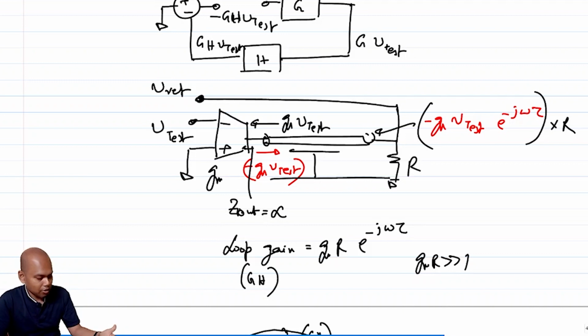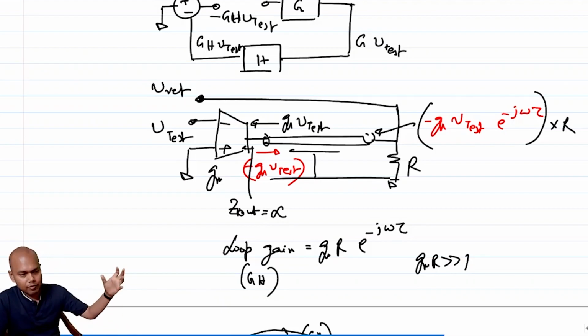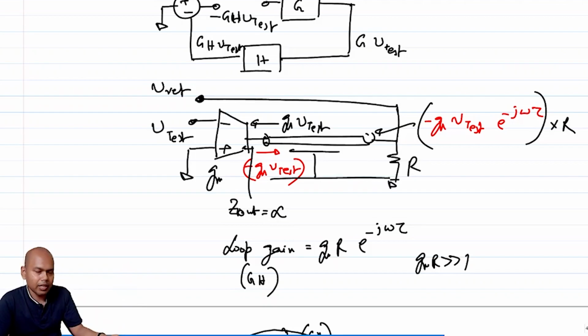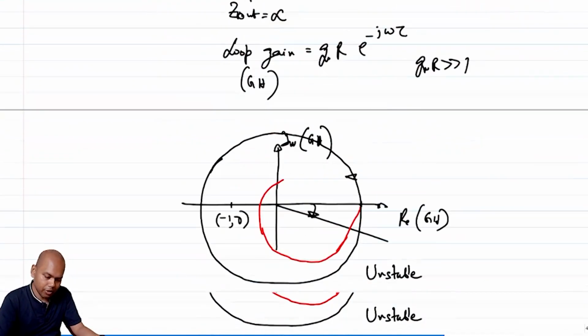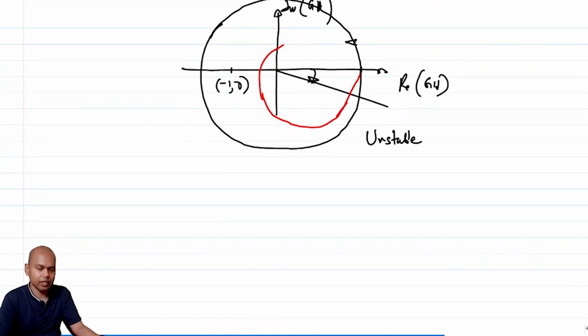So the issues, to summarize, from the perspective of a receiver: you can end up having intersymbol interference, right? Because if the signals are coming in and reflecting, and the next signal is coming in again, reflecting and interfering, then you might see intersymbol interference, and you will lose signal integrity and signal fidelity.